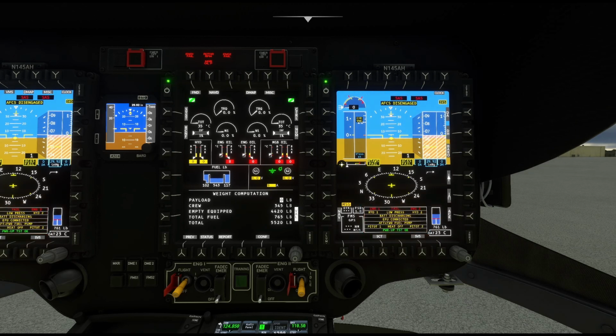So the main parts of the MFD are, of course, the master on-off switch. You got the 6 master select keys selecting the main mode. So these are line select keys in general, but the ones across the top are called master select keys. Then we have line select left, line select right, and bottom select. All right, and we number these 1, 2, 3, 4, 5, 6. Left select 1, 2, 3, 4, 5, 6. Right select 1, 2, 3, 4, 5, 6, and bottom select. Well, you get the idea.